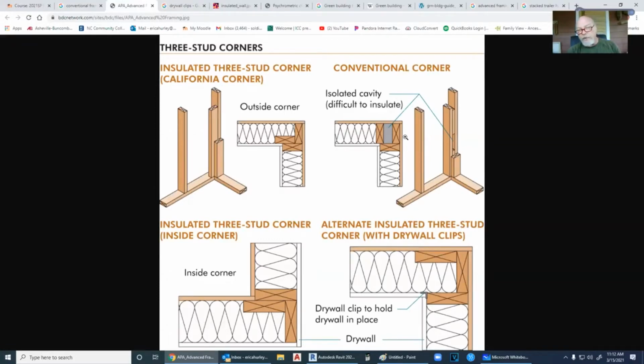So we've got the through wall here that we end up putting just 2 studs in. And then we have the butt wall that comes in that has its own stud. And that way we can get in behind it and put insulation in it. So now we have this little area here that's a thermal bypass. Before we had a larger area that was a thermal bypass. By doing this method down here, we're moving this piece of wood to the outside. All right, so before we had it to the inside, and now we've got it to the outside, which gets this away. We have less thermal bridging.